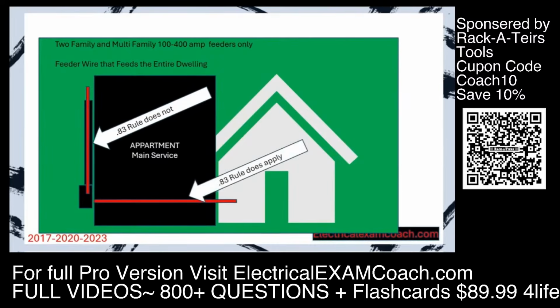The 83% rule does apply. And the beauty of this is it allows you to save money in the long run. Whether you're doing single family dwellings only or you're doing the individual units of the apartments, you're going to be able to use a smaller wire based off that table than you would if you went and sized it like normal. And over a year's time, that could save you a lot of money. So that is when the 83% rule does and does not apply.